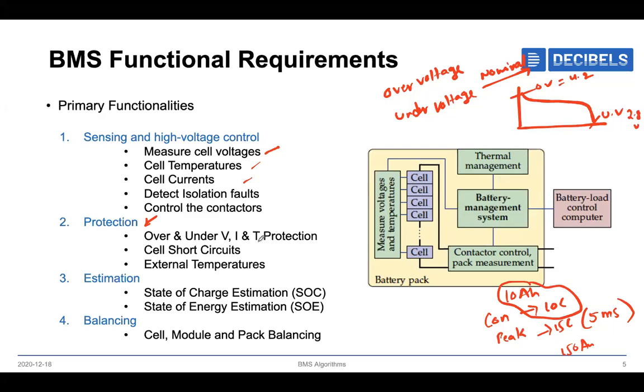And the third protection is temperature protection. So basically lithium ion cells, similar to voltage, also have a temperature range. So if you look at charging, it will be 0 to 40 degrees Celsius or 0 to 60 degrees Celsius. But when you look at discharge, it will range from -20 to 60 degrees Celsius. Okay. So we have to make sure that when we are charging the battery pack, this is the temperature that is maintained, at least in the vehicle or in the battery pack surroundings.